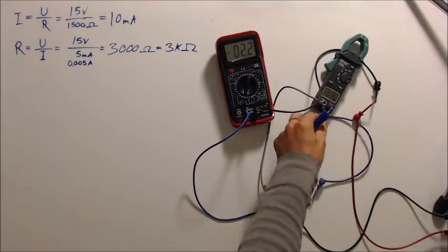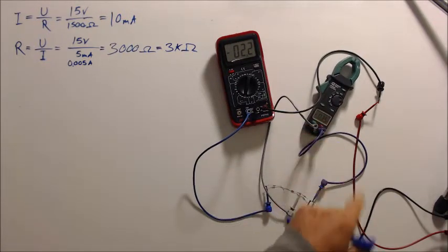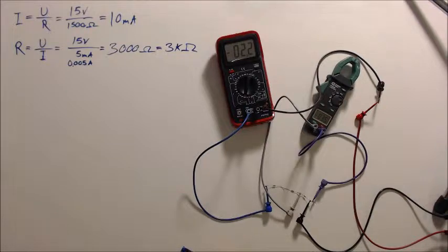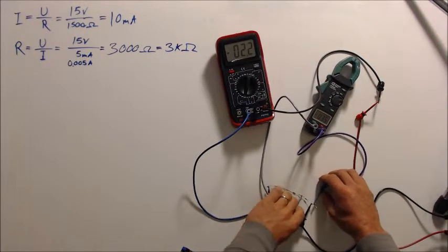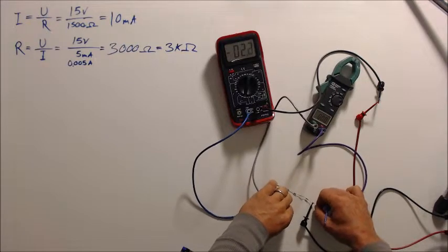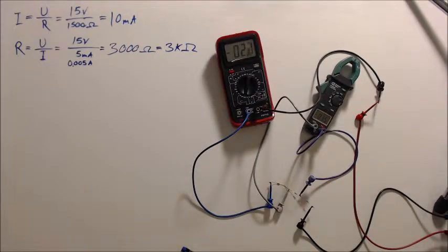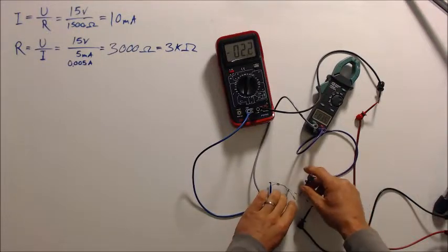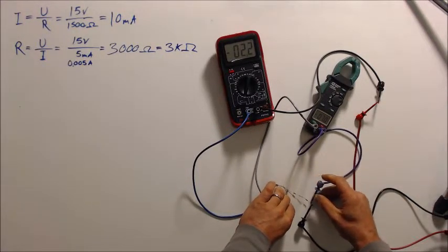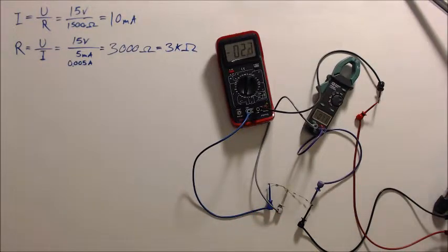But look then at this here. Our voltage across that resistor that we measured before has lowered even further. So let's see what happens if we measure across our next resistor, which is the same size. It has that same voltage drop as the one before. Let's measure them across one another like that. 7. So those two together, you can just add together, and you got 7.